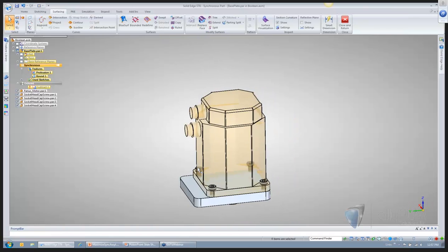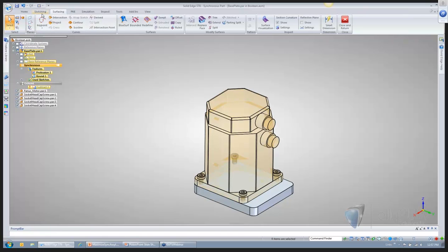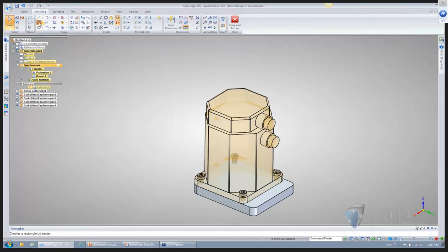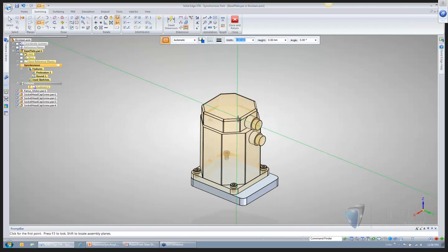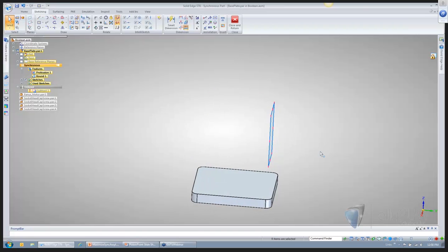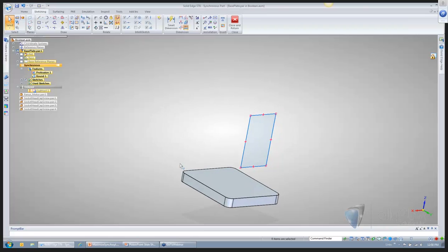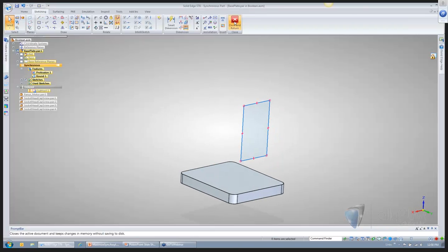And we can also now use the assembly reference parts for reference planes. So if I go to my sketching tool and I say I want to create a rectangle, I need to pick a plane. By holding the shift key now, I can now pick the faces of my assembly parts. So if I need to build a fitting that's right here, I can actually draw that and I'm in my part. So when I Control Q to toggle off my assembly, hide previous level, I now only see the plane relative to the part that I'm working at.